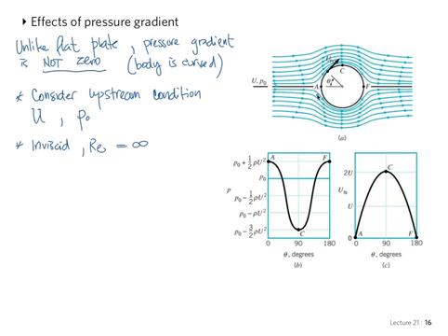So there's a variation of velocity, quite substantial variation of velocity from zero, the stagnation point. It is capital U at free stream, and it reaches a maximum velocity which is actually known to be 2U from potential theory results at this point here of, what is it? How do we measure theta? That's 90. Theta equals 90 degrees.